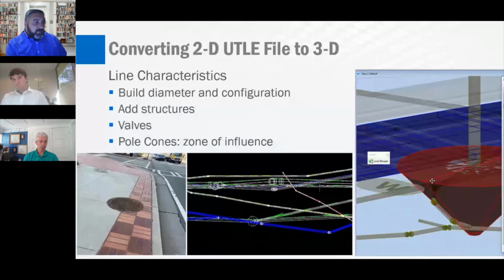For example, if you have a telecom duct bank within the project, typically a duct bank is a series of conduits that are most of the time encased in concrete. Given that you know the dimensions of the concrete encasement, either from records or from performing test holes, we can then note in the metadata the outer dimensions of the duct bank as we're depicting it in the file.